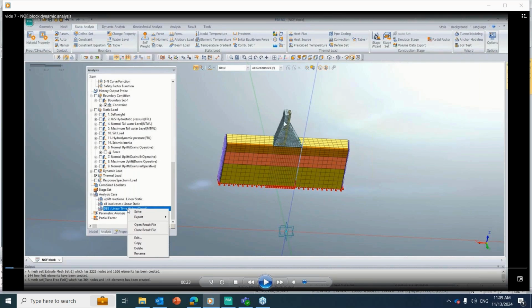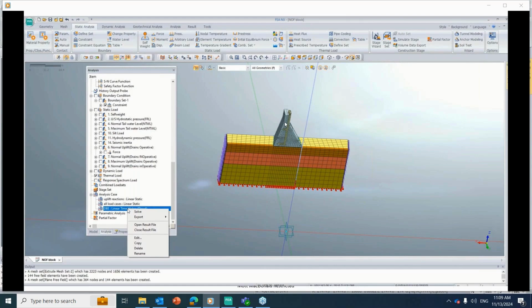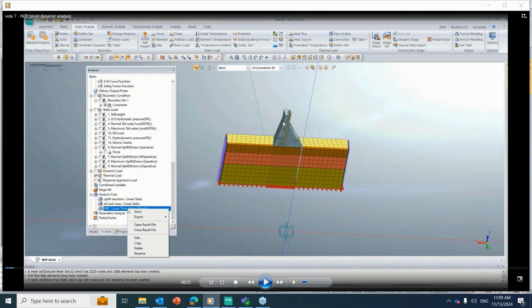That will depend on the damping, that deformation. Damping into the velocity with which this particle vibrates. So mass into acceleration plus damping into velocity. And the third one is the stiffness, the modulus of elasticity, stiffness into its deformation. So that will define the total induced force in that particle. So we have to solve our structure for all the forces for these three parameters only.